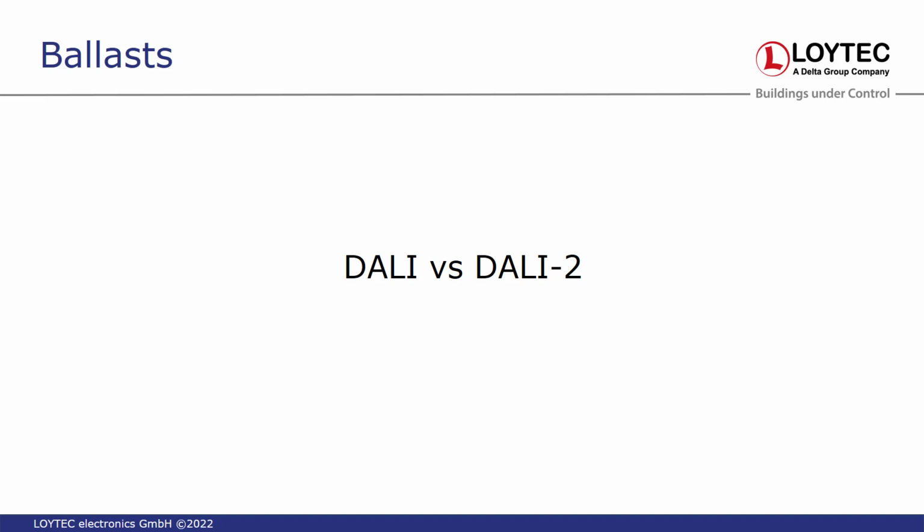And you are right that when you are DALI 1, or only DALI, this doesn't mean that it doesn't work with a DALI 2 device, or that for sure there will be some issues, but there is the possibility that there are issues, because there are also more restrictive timing definitions in the DALI 2 standard than in the DALI 1 standard.